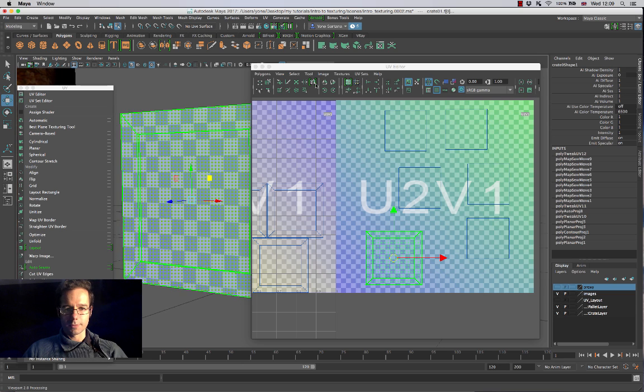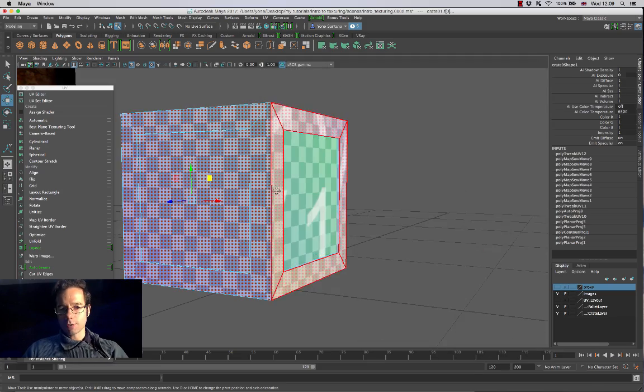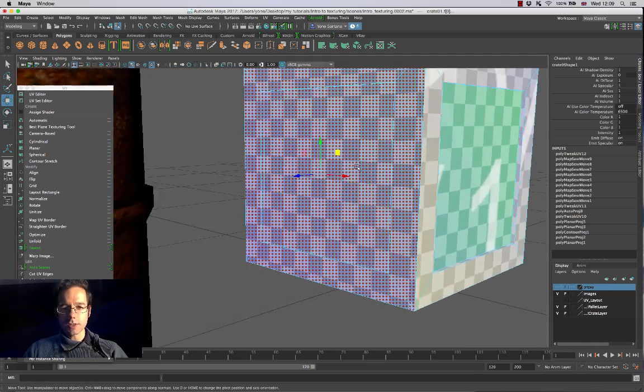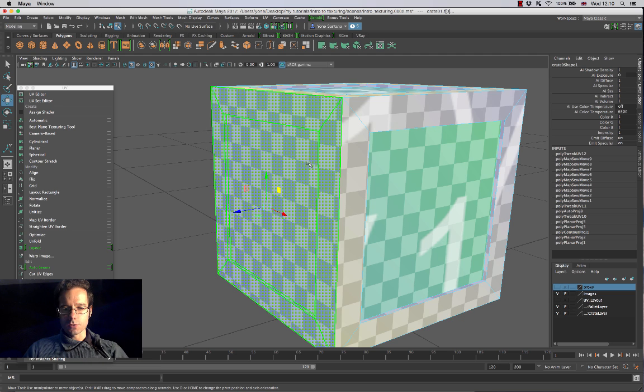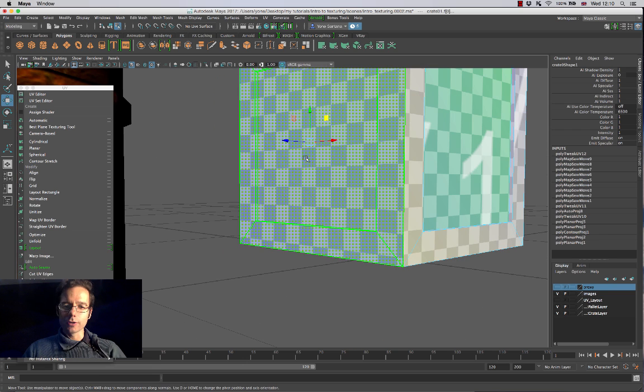That's a good segue for me to actually start talking to you guys about just another little thing that's important. Because we're still working with this idea that all of these UVs have to be as square pixels as possible, it's important that when you're laying your UVs out, all of the things that we've glued together should look like perfect little squares on top of our screen like that.